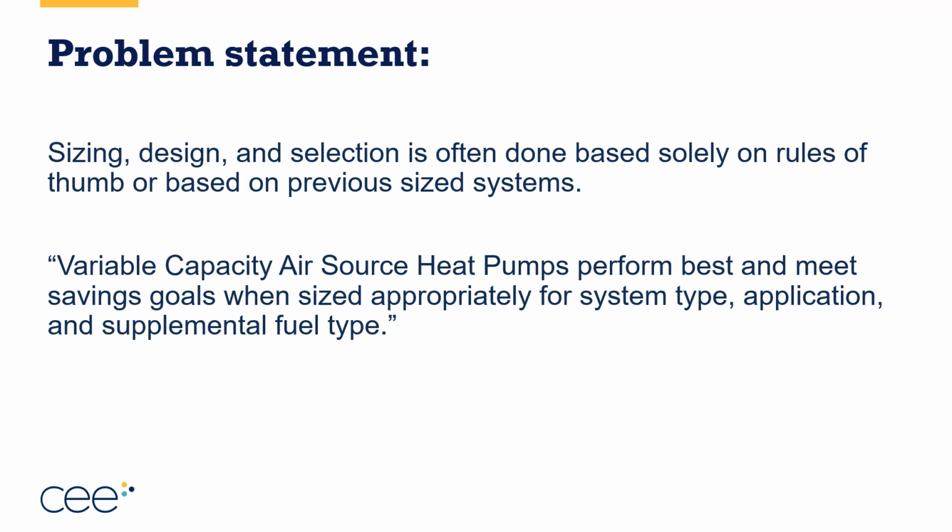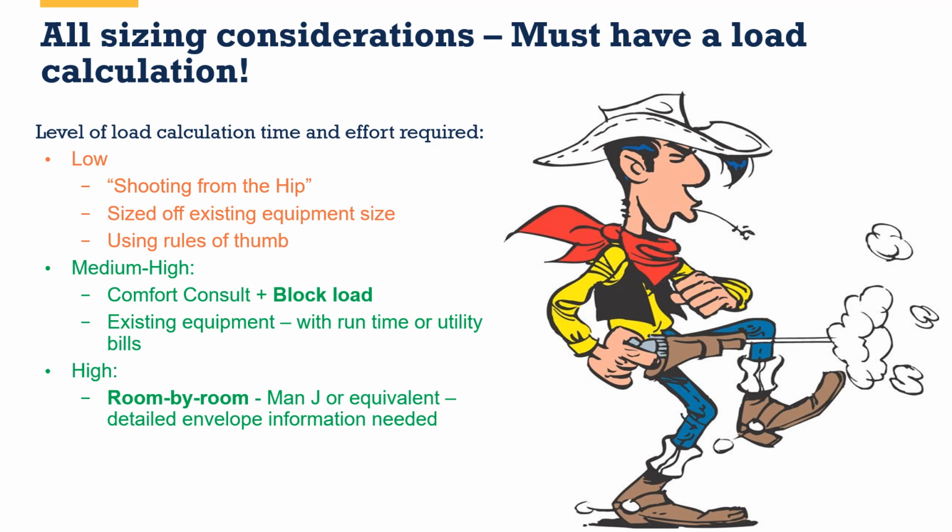But all of this goes to say that if we want our variable capacity heat pumps to perform their best, we need to factor all of that stuff into our sizing and our design, and load calculations is where we start. So I believe this to be true. All new systems should have some type of load calculation performed.